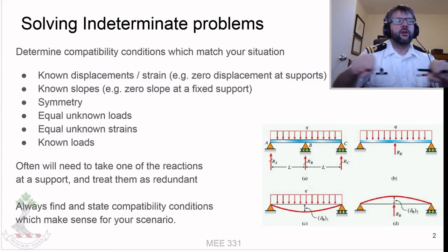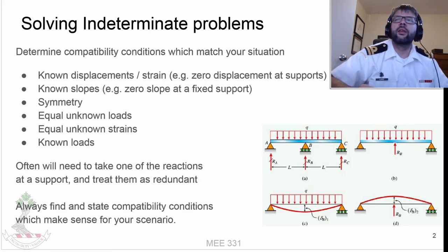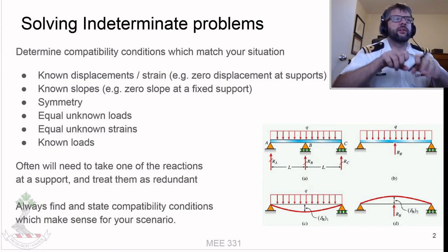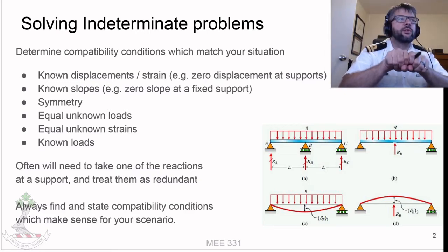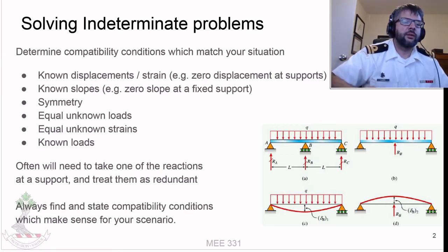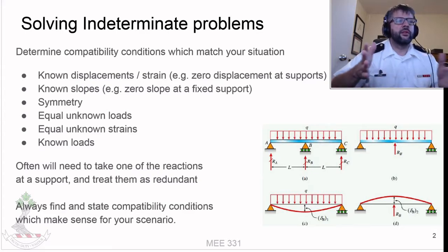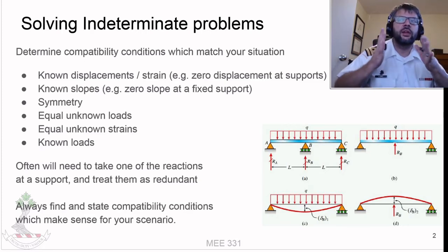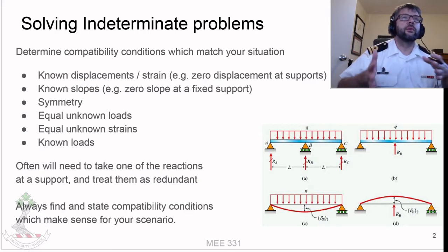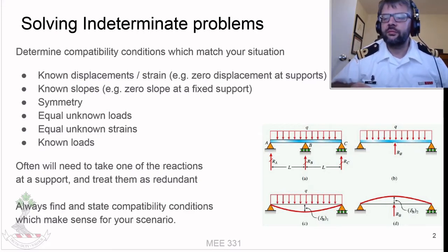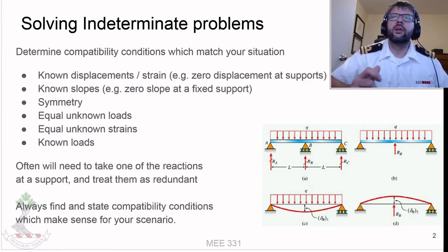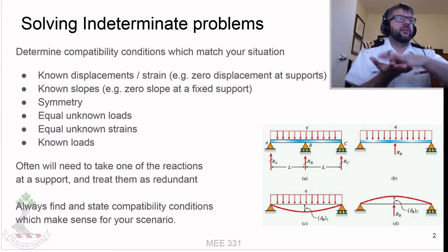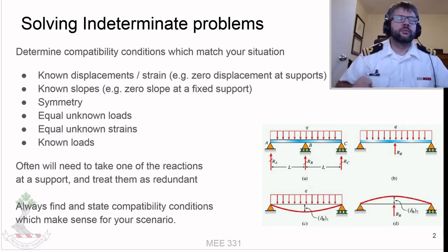If you're pulling along the direction of the fiber, then basically you've got the matrix material that's bonded to the fibers that are providing the structural support. That causes the matrix material and the fibers to have equal strains. We don't know what that strain is, but we know what they are relative to one another. They're equal.